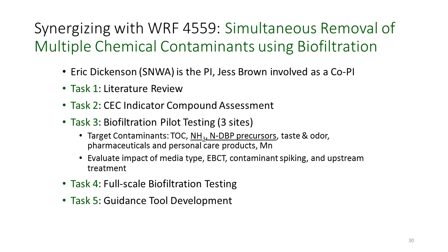Looking at high concentrations of some of these contaminants. And then upstream treatment, whether you've got some kind of preoxidant, how do you operate your coagulation process? Do you have ozone? Do you not have ozone? Task 4 of the project is full-scale biofiltration testing. This is where American Water heavily comes into play. So we'll be looking at